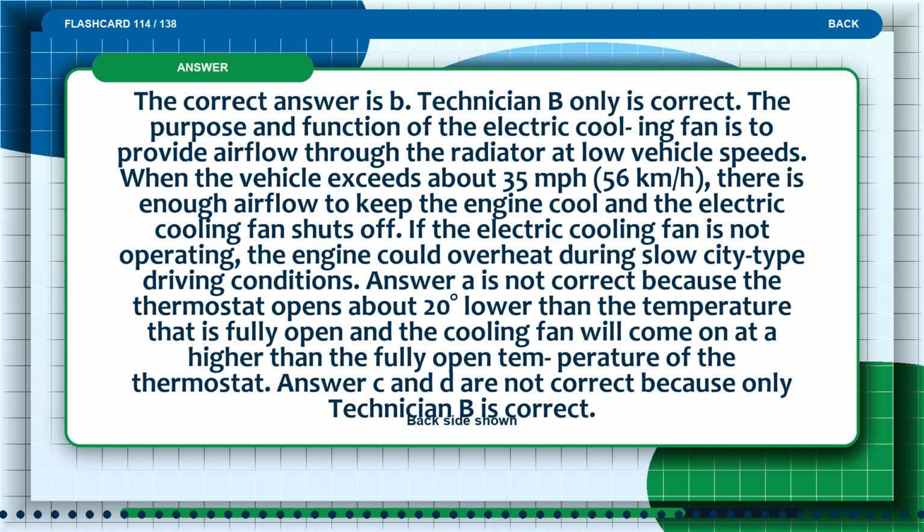Answer A is not correct because the thermostat opens about 20 degrees lower than the temperature at which it is fully open, and the cooling fan will come on at a temperature higher than the fully open temperature of the thermostat. Answers C and D are not correct because only technician B is correct.